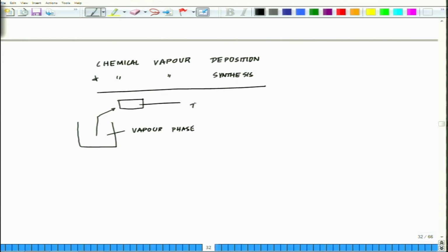It is used for all sorts of thin film deposition on a substrate, most likely for thin film synthesis. Okay. So, thin films produced by CVD processes at certain conditions also contain ultrafine particles. Hence, the synthesis of nanomaterial can also be possible by this method if the CVD system is modified. Say for example, you have high temperature in a hot wall reactor, high supersaturation or low residence time and a small substrate. If you have all these parameters and you really want to use a very small amount to synthesize nanomaterial on a substrate, then the best idea is to follow CVD.